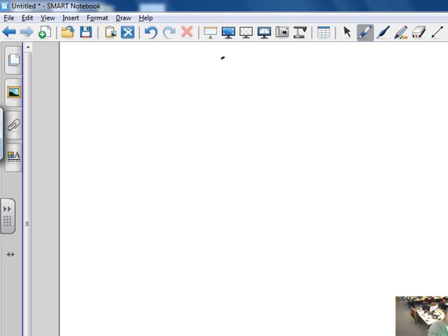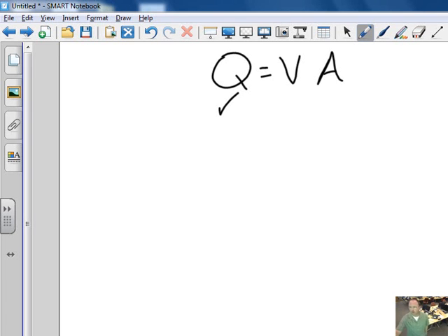We talked about Q equals VA. And we know how to calculate Q, whether we do Q equals CIA, which is the rational method we've talked about so far. There's a couple other ways of calculating Q that we saw off the DOT. We now know how to calculate A for a cross-sectional area. The question is, how do we calculate V for an open channel?